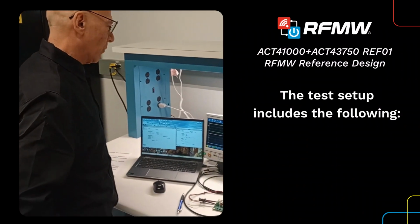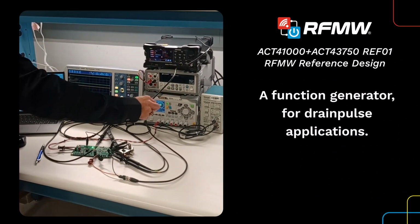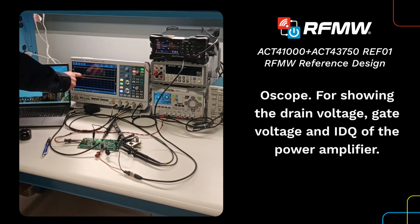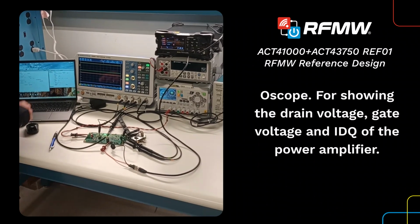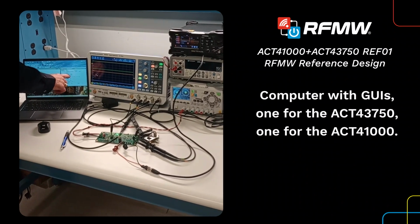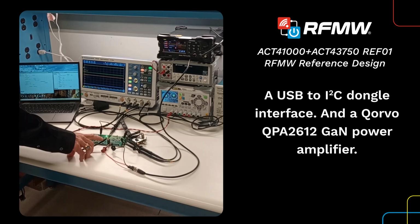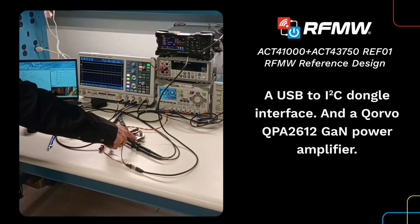The test setup includes the following: a 40 volt max input power supply, a function generator for drain pulse applications, an oscilloscope for showing the drain voltage, gate voltage, and IDQ of the power amplifier, a computer with GUIs, one for the ACT43750 and one for the ACT41000, a USB to I2C dongle interface, and then a Qorvo QPA2612 GaN power amplifier.